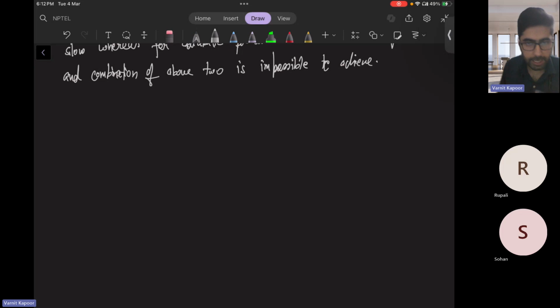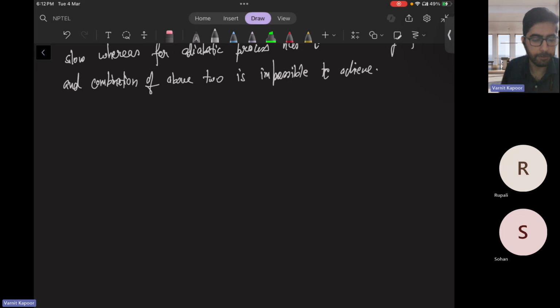Next, the area under the pressure volume curve gives us basically our work. Okay, we know that very well. But here there is a very narrow region in the pressure volume plot. If you have observed the graph which we plotted in the last tutorial, that was quite a narrow region because adiabatic has a higher slope compared to isothermal. We have discussed this: gamma times the slope of the isothermal process, because of which the region comes out to be very small. So that's why the work obtained is also very little. Okay, that is one of the drawbacks of the Carnot cycle.